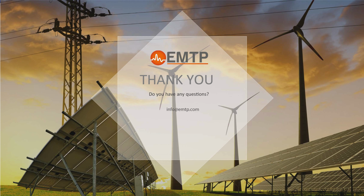Right, makes sense. You mentioned that you have been using generic EMTP PV models from the renewable energy toolbox. Have you done any modifications to those models, or if you did modify something, what was it? Yeah, the main modification was the addition of the onboard protection based on California Rule 21.